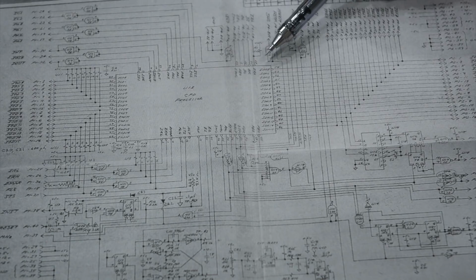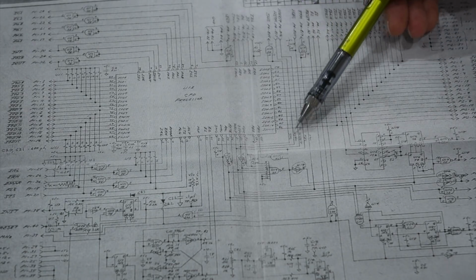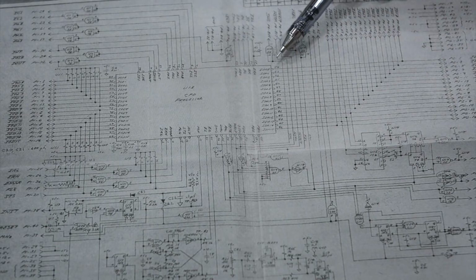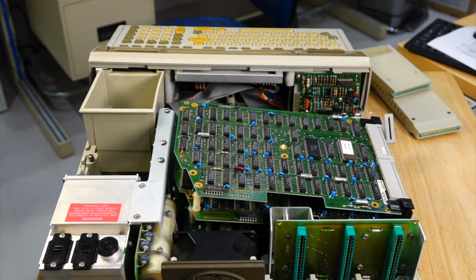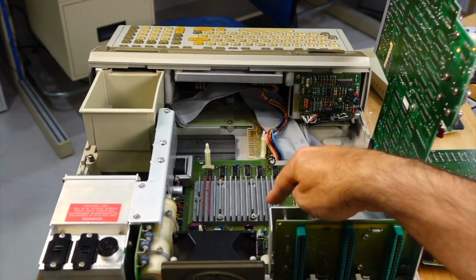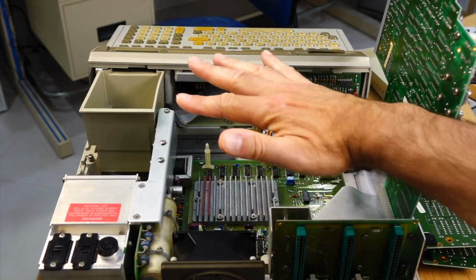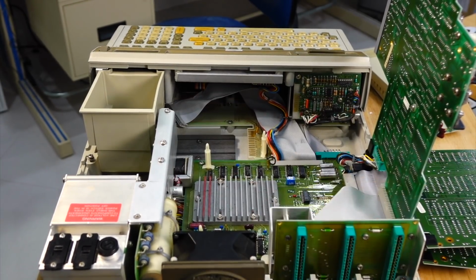But the bus we're interested in is the 16-bit bus over here, which is both data and address. So it's multiplexed, which is going to make our life very annoying. Sometimes it's data and sometimes it's address. The question is where to probe the bus from the machine. Not on these connectors, because these are hooked up to the I/O bus, which would be the wrong bus. The processor, as you can see, is compressed, so you don't have access to the pins.